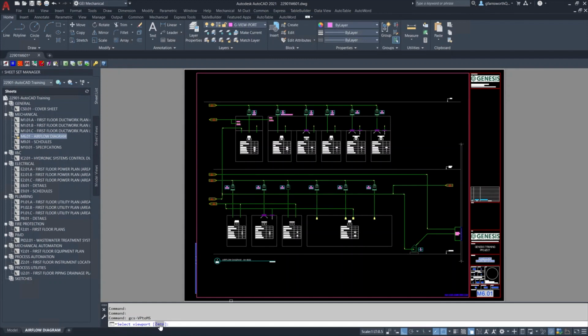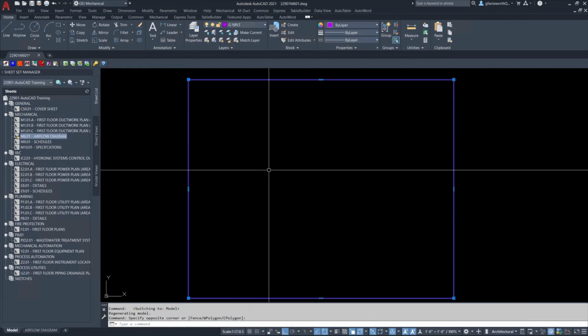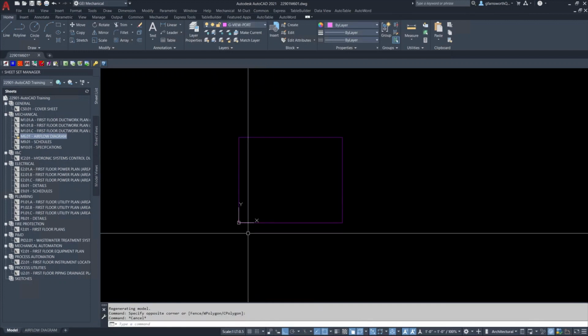Then select the 0 option. 0 is a special option for this process. It will place the bottom left corner of the referenced rectangle at 0, 0, AutoCAD's origin point. It will then zoom your viewport to the rectangle's location. Using the 0 option makes things nice and orderly for linking into Revit.